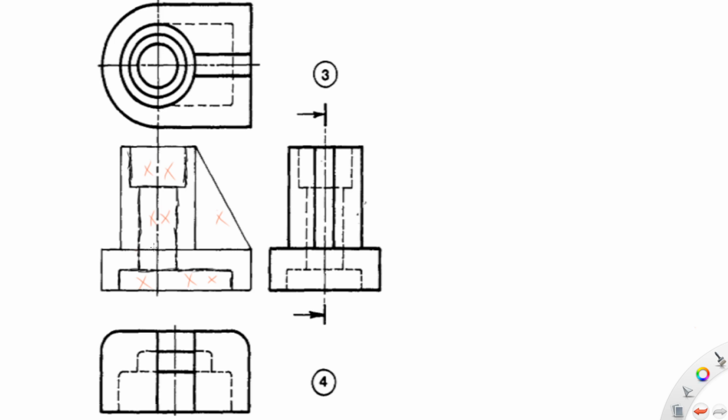It should not come. Because now when the cutting plane goes through the material, that line would have shown the edges at the end here, these edges here, or those edges over there. So they will not appear when the cutting plane goes through. It will reveal the inner area of the material. Those lines will not appear.